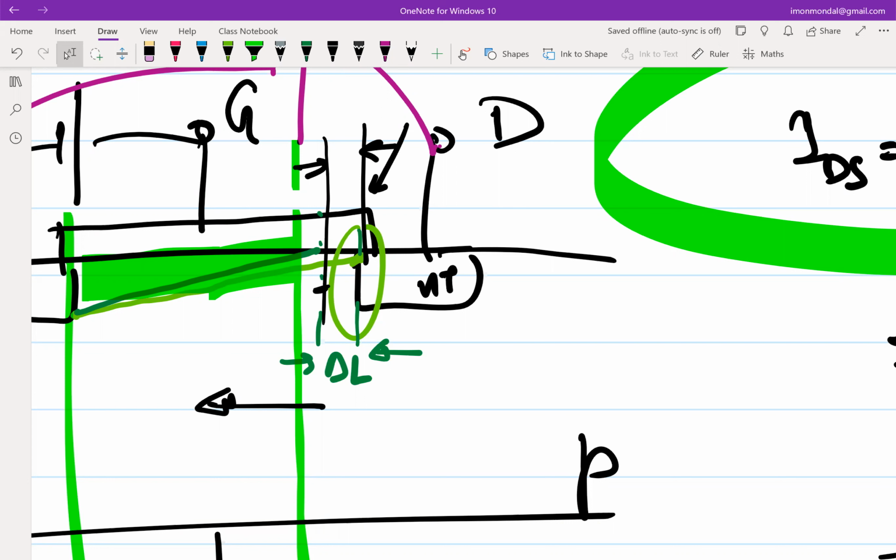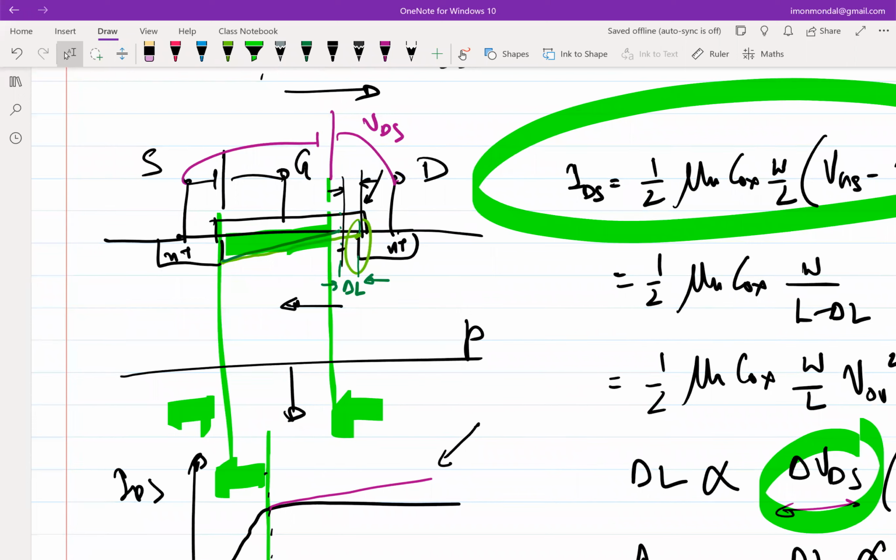So when the body is P and you have applied VGS or VGB, the first thing that happens is you deplete all the holes and you get some ionized impurities which are unmasked, right? So you'll have Na minus, immobile charges that will get unmasked first. Then if you keep on applying higher VGS on top of whatever you started off with, you will see mobile charges, right? So that essential concept was that of threshold voltage, right?